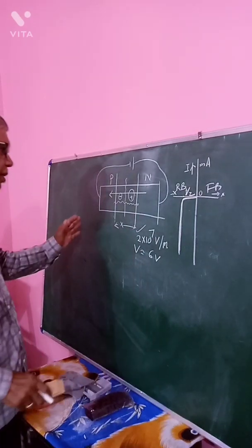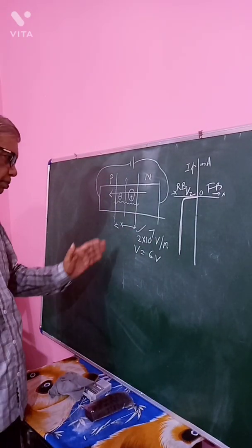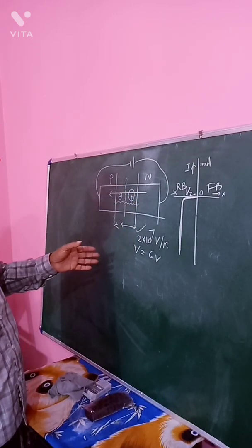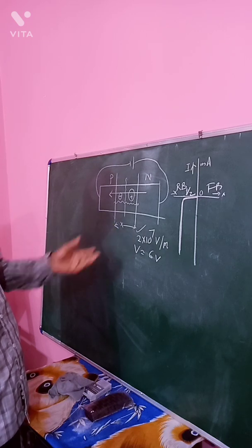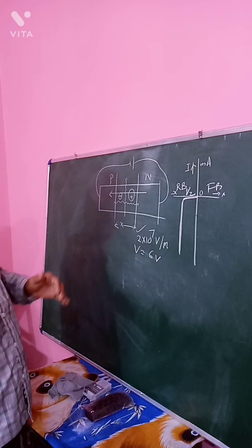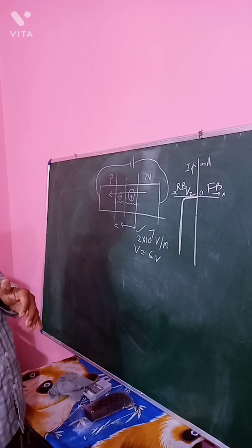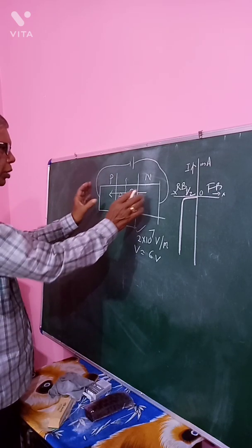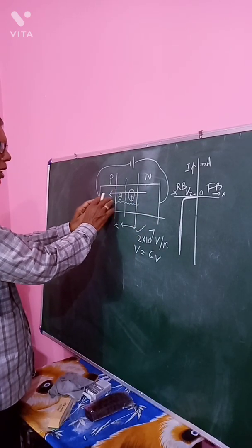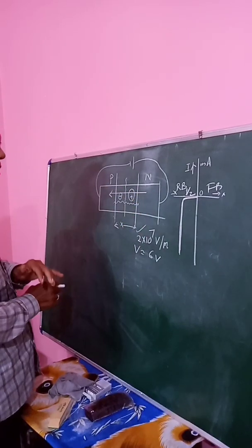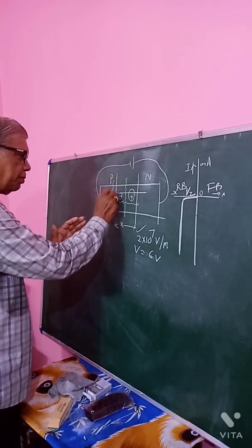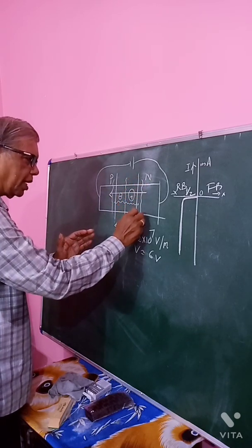Now this is the Zener breakdown, and Zener breakdown is reversible. The moment you switch off the electric field, the system comes back to the original configuration. Now another mechanism for producing a large amount of current is avalanche breakdown. In avalanche breakdown, the doping of P region and N region is light, is small, as a result of which the width of the depletion layer is comparatively large.